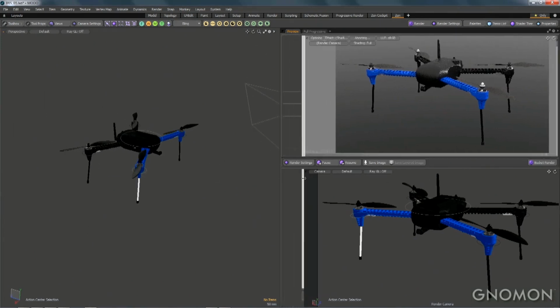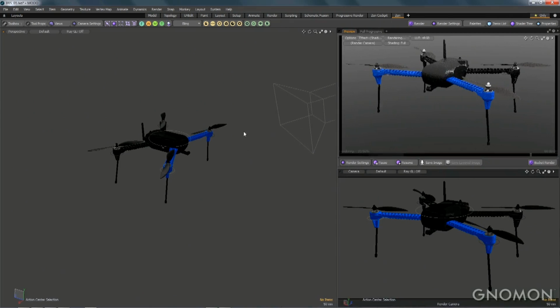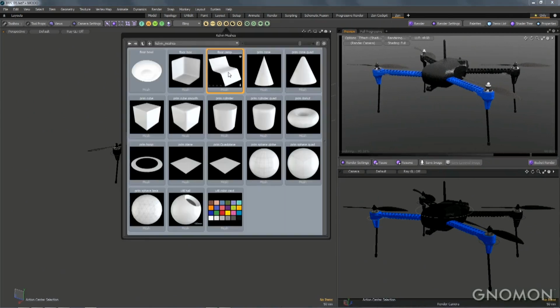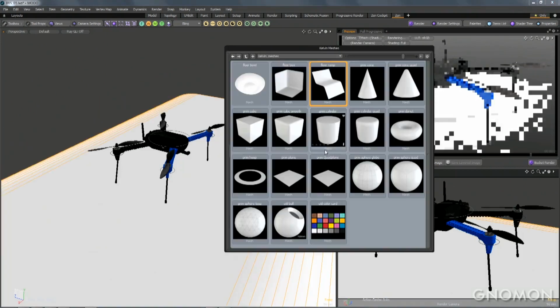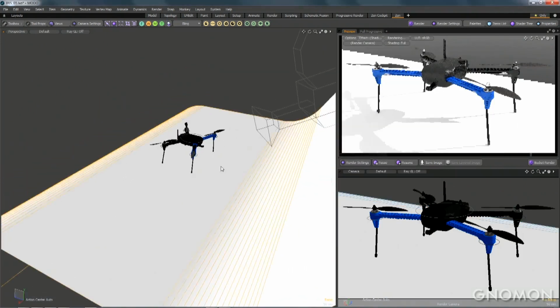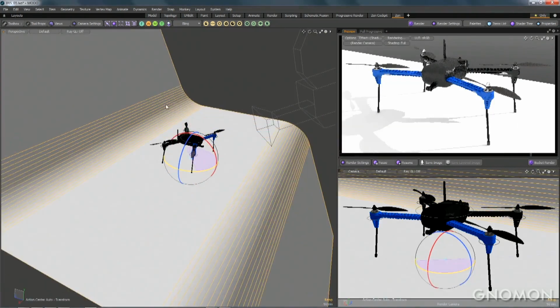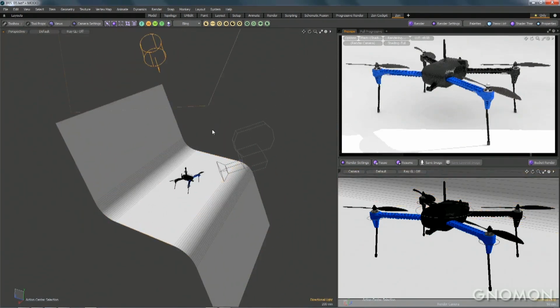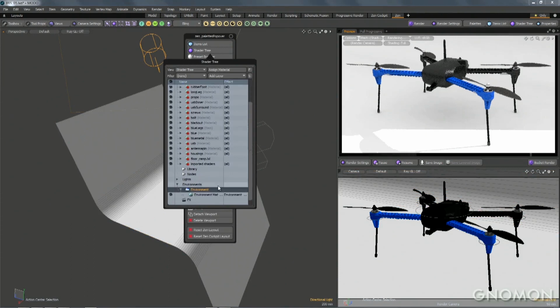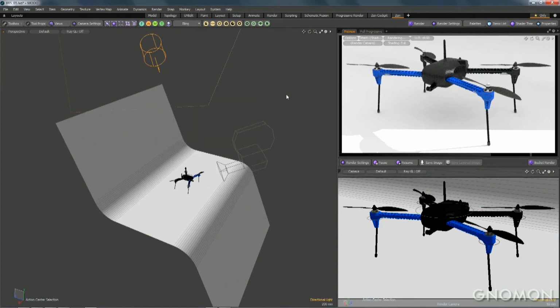Now, Kelvin is our studio photography kit in Modo. Studio photography is obviously a huge part of what we do, and so this one is really important to our work. It's probably our second most popular kit. It's really fantastic. Here I'm just dropping in a really basic ramp for a typical studio shot. It asks you for the scene scale when you drop it in, so you don't have to do any scaling after the fact. The default scene has a directional light and a glowing environment by default.